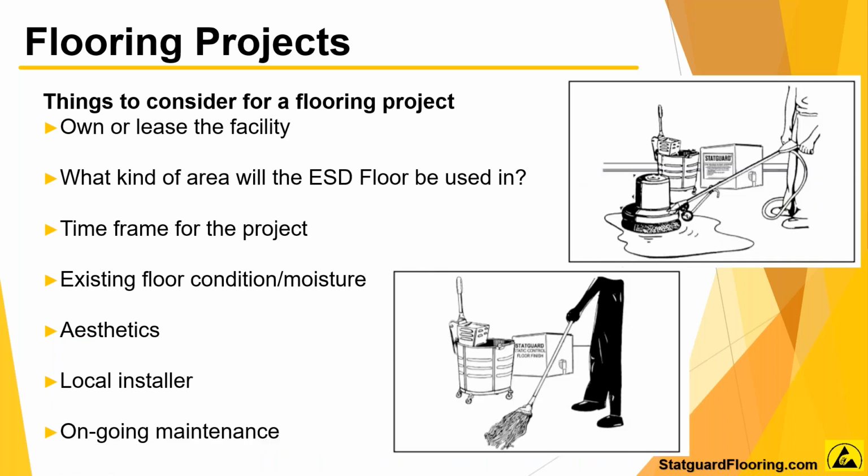A floor maintenance plan is very important as an ongoing process to maintain the look and the electrical resistance of the installed flooring. Preventative maintenance is important to maintain the electrical properties and the appearance of the ESD flooring. We recommend installing tacky mats at all entrances to the ESD protected area to help remove particles from the foot grounders before entering the EPA.